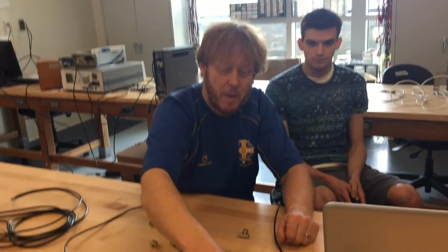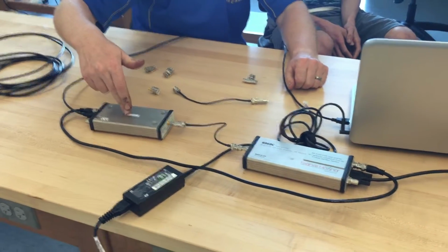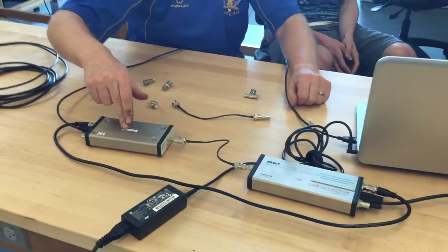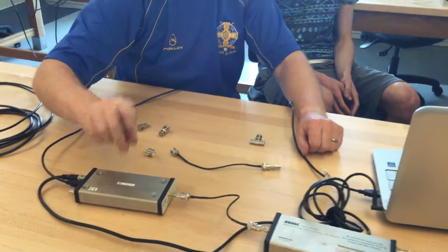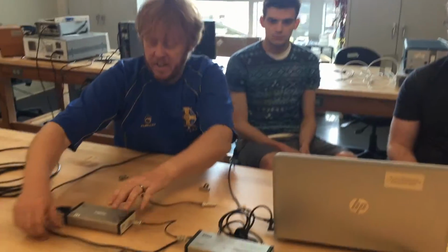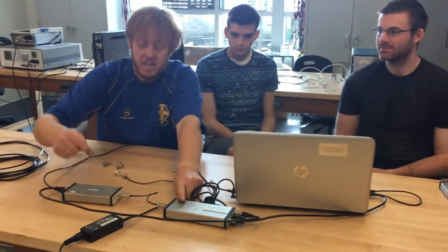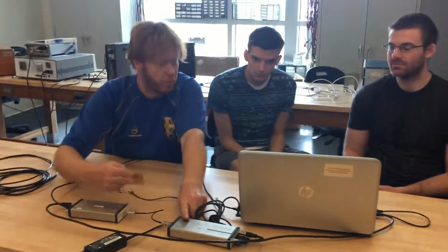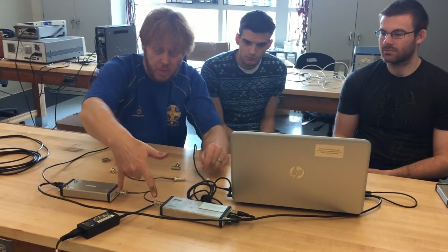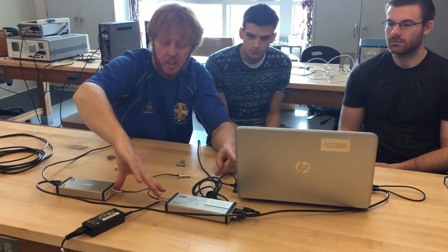We have the spectrum analyzer, and we have a thing called a tracking generator. This sends a signal from 0 to 4.4 gigahertz, which is an amazing capability. It sends it into the spectrum analyzer, and this cable synchronizes everything, so the spectrum analyzer knows the tracking generator is sending a signal of a particular frequency. Then you put something in here. So we have them talking, we're going to normalize the curve. We'll take you around in a second and show you the curve.